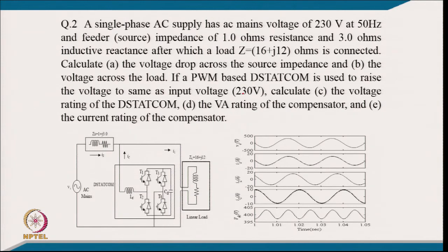After getting proper design and control, these are the waveforms after the simulation. You can clearly see the supply voltage and supply current, and the supply current is supposed to be slightly leading. This is the load current, and this is the compensator current, or you can call it the current drawn from the supply, and this is the DC link voltage, which certainly carries a second harmonic.